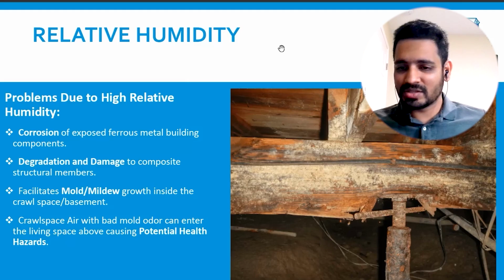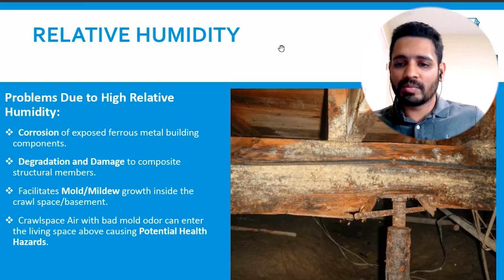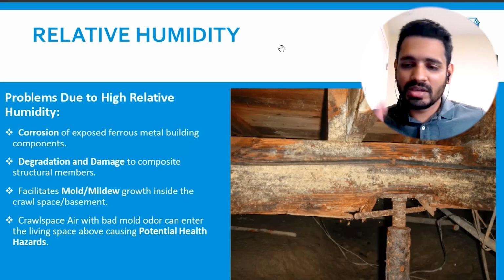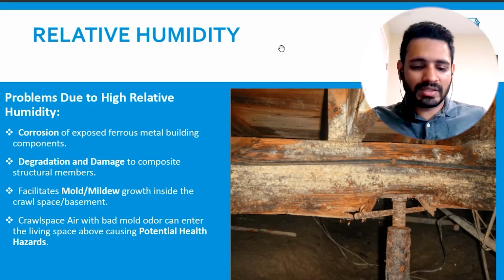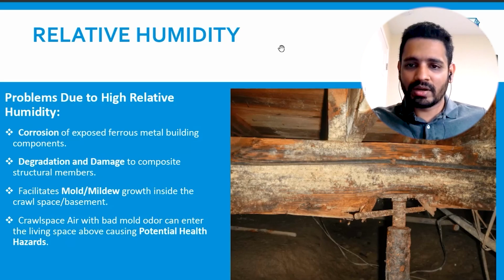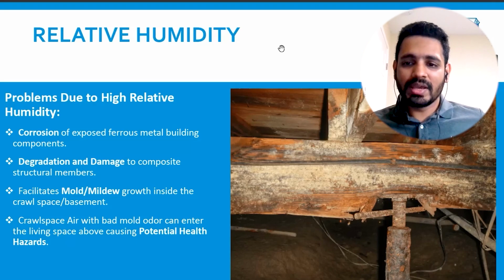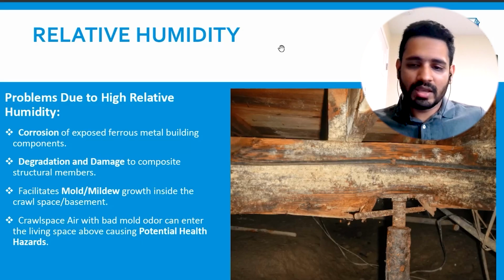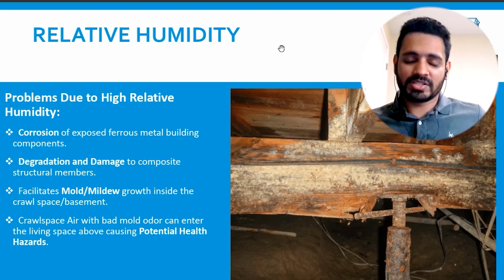And because it's metal, even if it goes through a good amount of corrosion or damage, it can still support the weight that comes down on it. Having something that can support 2 times what's required versus something that can support 10 times what is required is the difference that we're seeing between a wood post and a metal jack, for illustrative purposes, right?